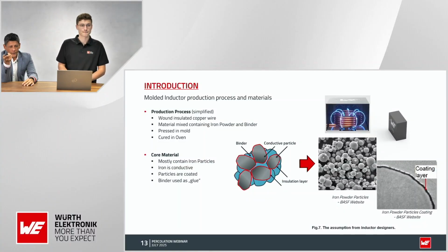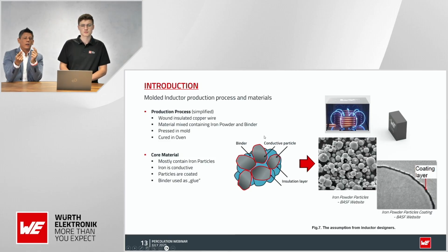Now we can see here how we add this kind of coating. If you increase the coating layer, then the question is going to be, okay, and what happens with the permeability? When we have this kind of behavior, we see that all the magnetic field goes through all the particles here in order to save energy and release that energy softly. But if you have a thicker coating, then you change the air gap, and you decrease the saturation performance.